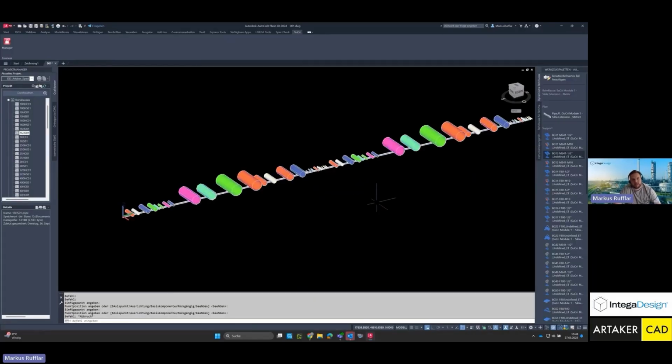Of course, some people might say, well, I could just create a DWG once and save it. Yes, you could. But let's say in the pipe class, the nominal sizes change, new sizes are added, and so on. Then I'd have to manually add the missing sizes every time. With this, I just click once and it really inserts all the pipelines from my spec, from my active spec, with a suitable support, and I can start testing right away.